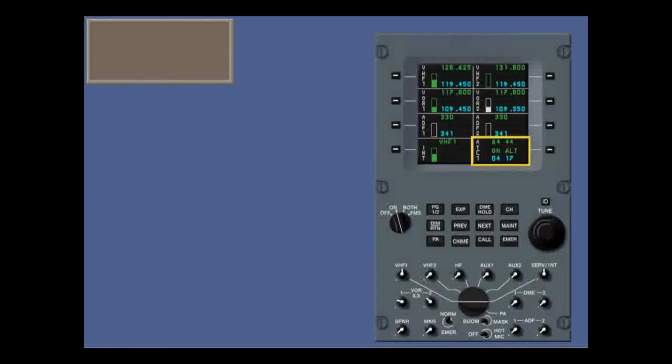Displayed on the ARC2 ATC window are the active ATC label, so ATC2 is on standby, the active transponder code and the pre-selected code, the transponder mode, on or standby, and ALT if altitude reporting is on. When transmitting an ident to ATC, ID appears next to the pre-select code.